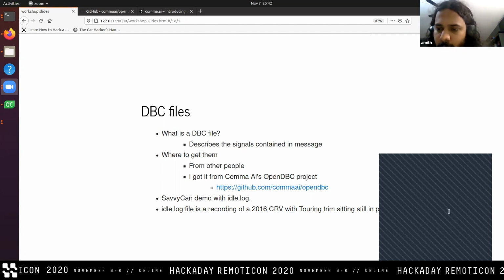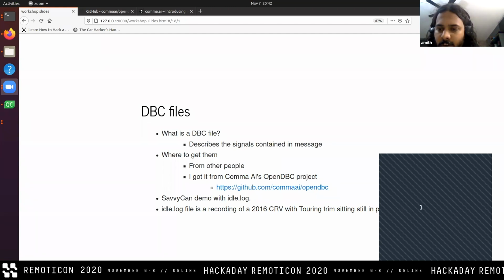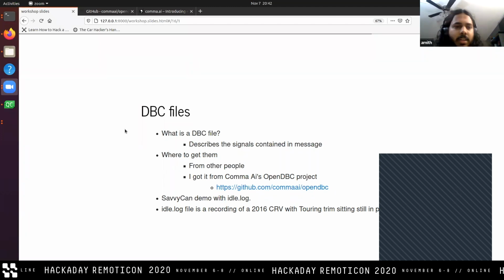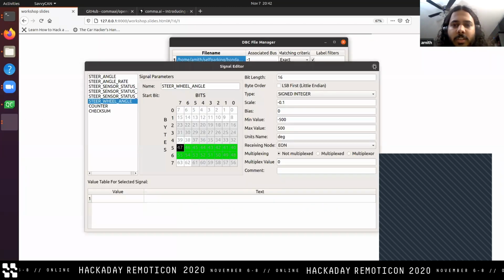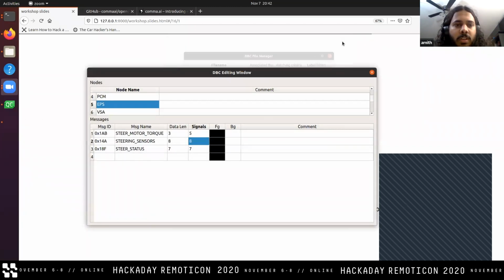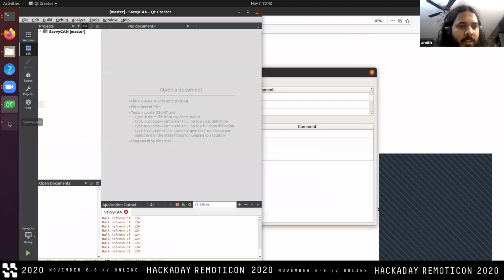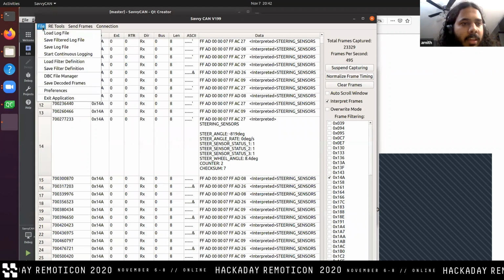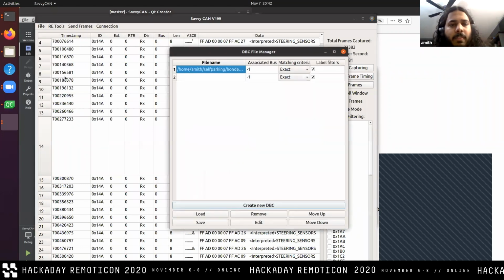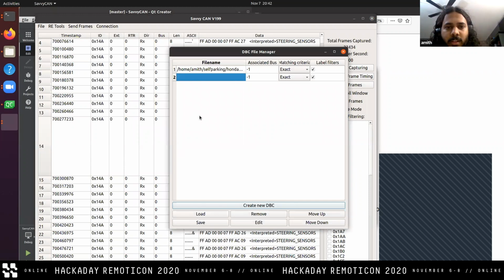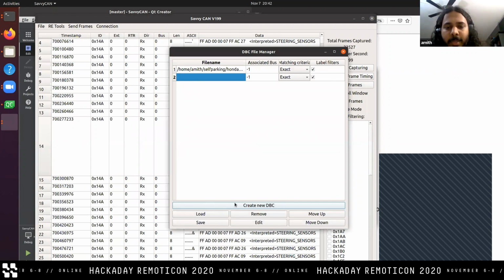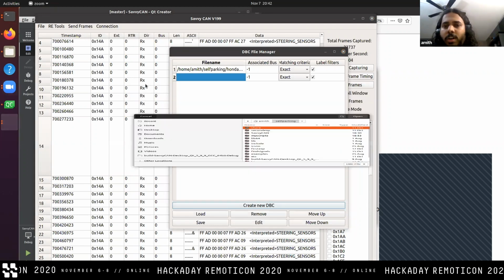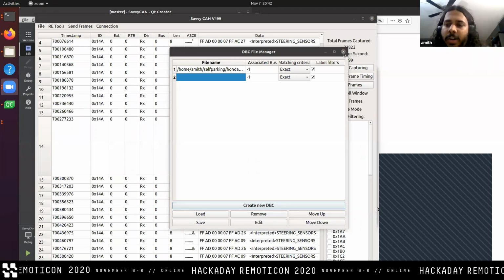There's a lot of questions that I went by, so I'm just going to make sure. Okay, so there's a couple of Savvy CAN questions. I'm going to, hopefully this doesn't close down. Okay, there we go. To load a DBC file, you go into DBC file manager, and you can either create a new DBC file or you can load one, and you navigate to where you have it stored and you load it in. So it's very simple.